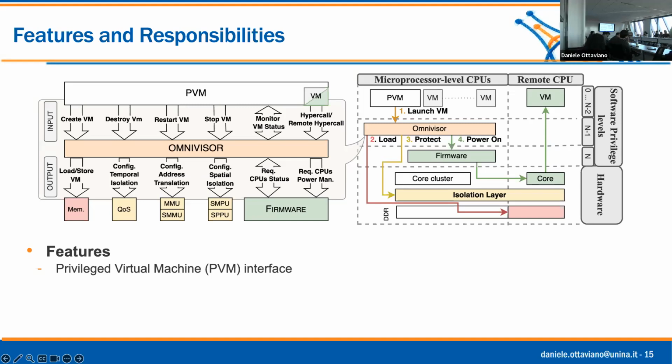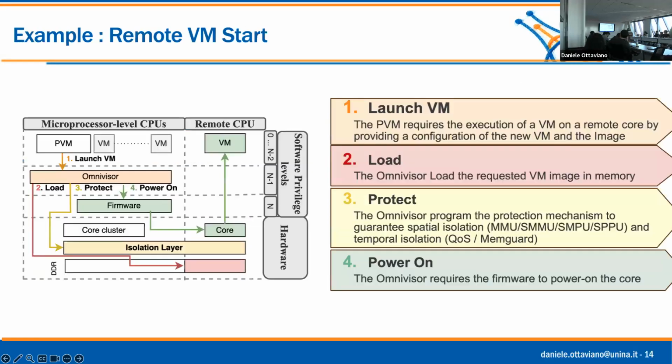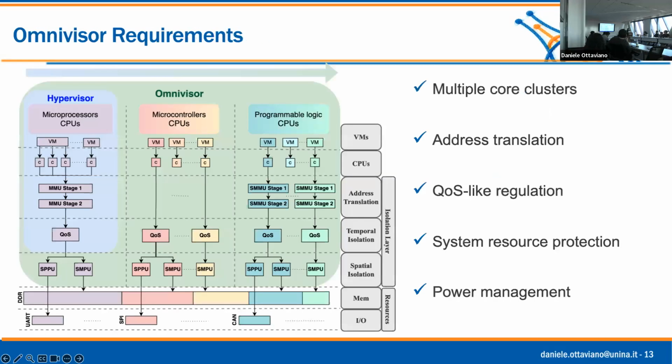But if you go back to the mechanisms that you had, what were the mechanisms to give you the partitioning? You can also go through an MPU from the FPGA, right? So why wouldn't you want to do that? Why would you want to use the SMMU? The SMMU gives you virtualization and partitioning, but you can also have a second layer of privilege through the MPUs. Right, so MPUs give you just the isolation, but no translation. Is that good enough for most things, or do you need to use the IOMMU?